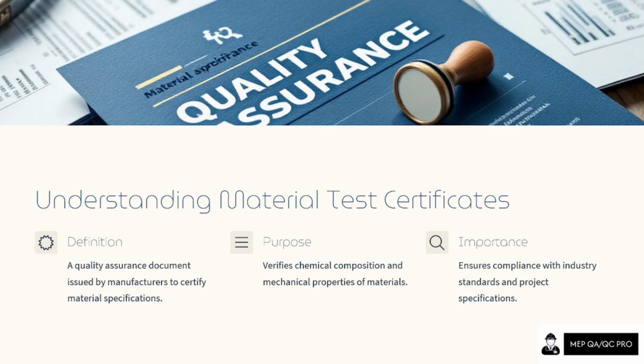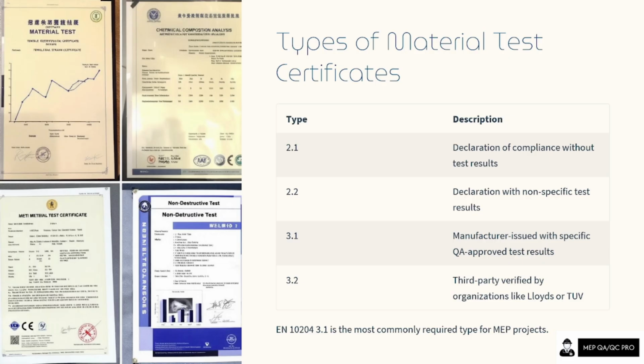You need to send it to them and ask, as per the delivered material, kindly provide the material test certificate as per the attached DO. So you will get the material certificate from the supplier based on the delivered material. They will not send you any other test certificate. After that, you need to verify that test certificate. How you will verify, we'll see in the next chapter.